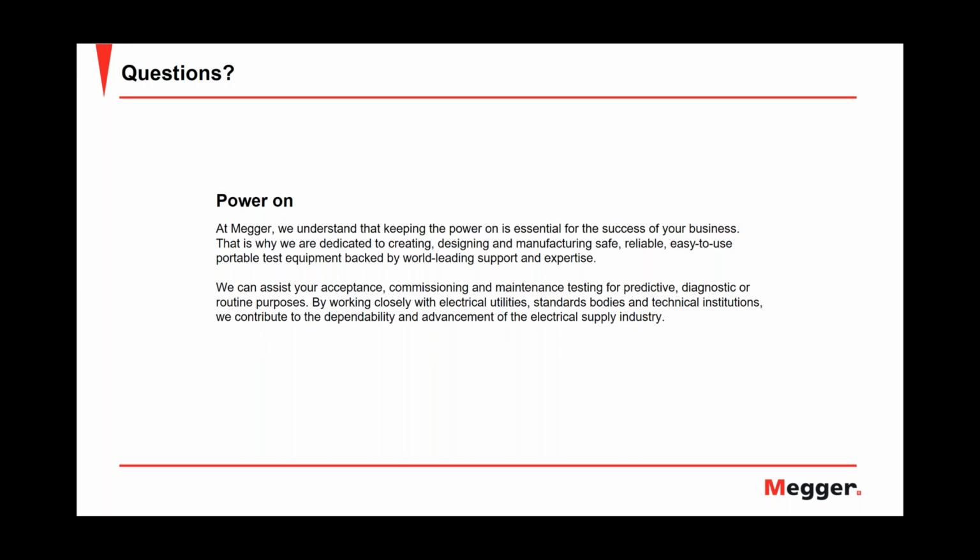And ARM stands for arc reflection method, because the TDR, like Javier was explaining, on a pinhole fault cannot find the pinhole fault, because we need maybe a flashover voltage of a couple kV, and the TDR signal is only a couple volts, maybe 50 volts. So we have to help the TDR by providing a short circuit at the fault, by putting a high voltage on, which creates a flashover. In the moment where we have a flashover, we're using the TDR now and shooting the radar pulse in, and the radar sees a short circuit and gives us a negative reflection. That is how that works, and that's why it's called arc reflection. Without an arc, I cannot do the arc reflection method. That's what Javier was saying. If we have a dead short, there is no arc, I cannot find it with the arc reflection method.